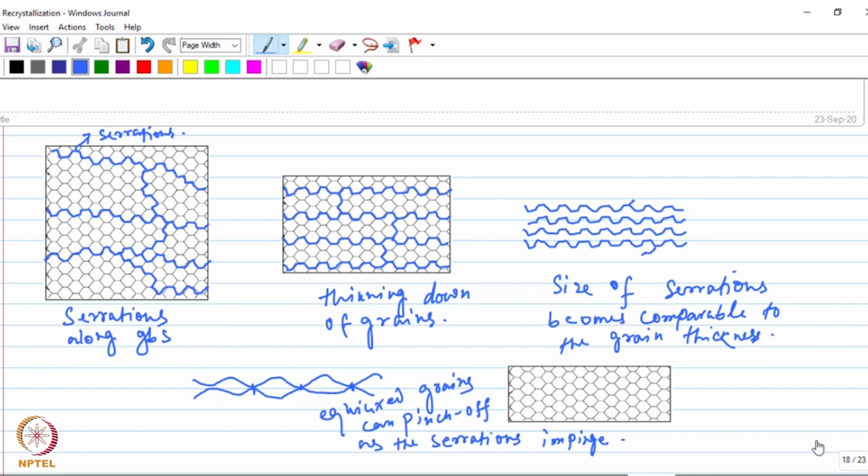All right, so one thing you would have realized by now, in all these dynamic recrystallization mechanisms, the new grains which are forming are actually not only recrystallized, but they are also finer in size, right? In every mechanism that we have discussed, whether it is DDRX, CDRX, or the GDRX, we have seen the new grains which are forming are equiaxed finer grains, right?